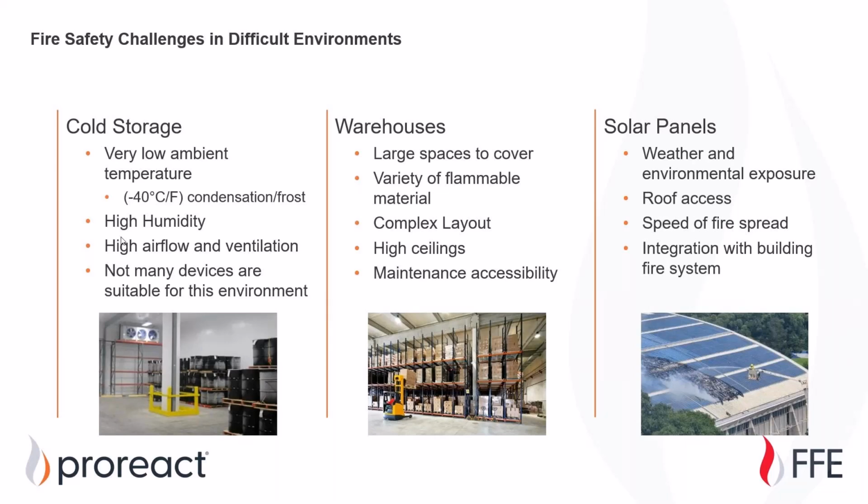With the humidity in these cold freezer, cold storage areas, they can be very susceptible to frost forming. So if you have an individual device, say a heat detector device, smoke detector device, sometimes these can just turn into a ball of frost or a ball of ice in these environments. So with linear heat detection cable, it is suitable for these environments. They do have an IP67 rating as well for ingress protection and moisture proof.